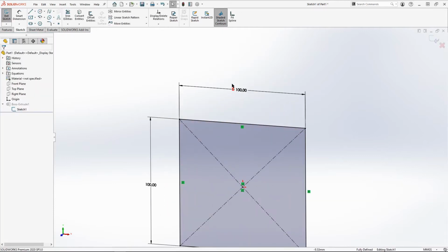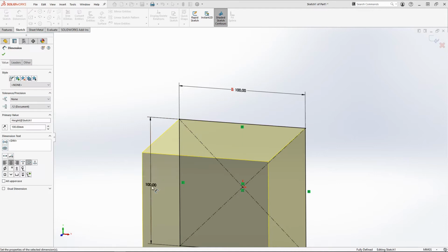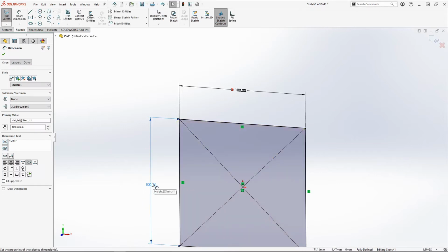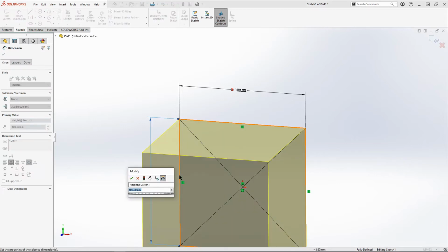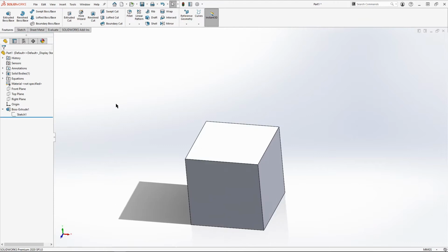So you'll see it adds an epsilon sign there, saying this is now equation driven. Now if you don't put in the equal sign, if you just select the global variable, it'll add the value, but it's not going to update when the variable updates. So it'll grab the value once, whatever it is currently, and then continue using that one value all throughout. So we're just going to set that equal as such, and there we have a part.